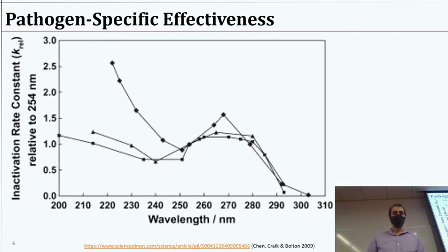So, for example, these ones were probably created with xenon lamps with UV cutoff filters so that light only in this window can make it through, and you expose your system. It's an expensive lamp. It's fancy. It probably wears out quicker than the fluorescent ones, and it's kind of a lab scale test. So we can do some of this testing.